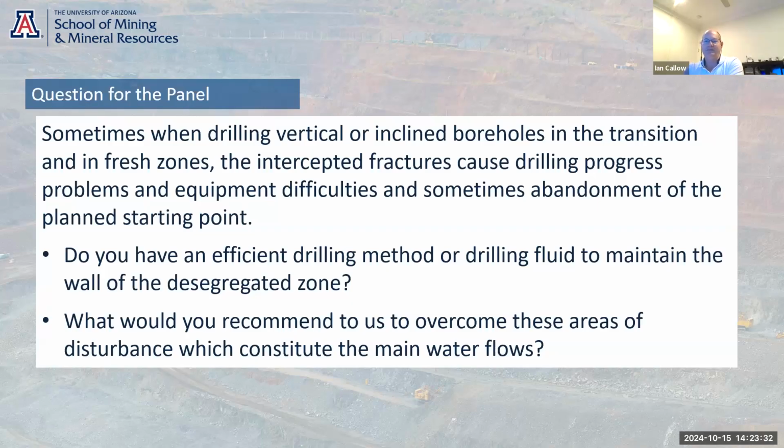So got the casing to TD, dropped a well screen inside the casing and pulled back to expose the screen. So it was an adaptation of the very old-fashioned percussion method of construction, with a rig that was really set up for just pretty much conventional rotary. So sometimes you have to adapt and work something out. Yeah, and not screw up the hole with bentonite.